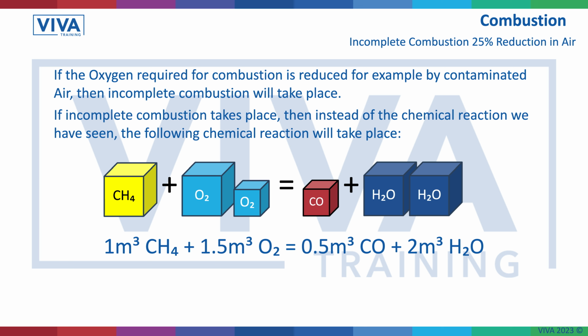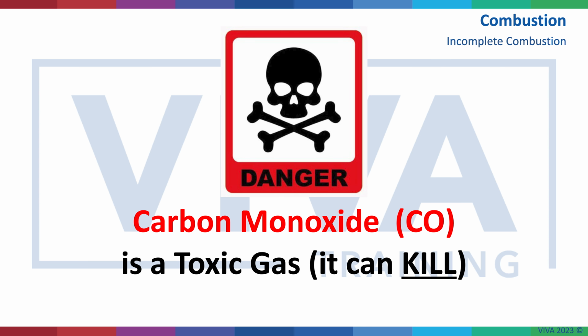So ventilation is really important, and the amount of oxygen that we get in to give us complete combustion. Carbon monoxide is a toxic gas, and it's a killer. People do die from carbon monoxide poisoning. That's why now, as best practice, we should be fitting carbon monoxide detectors wherever there's a gas appliance. We should have a carbon monoxide detector in that room, tested on a weekly basis by the customer, making sure that they're safe.